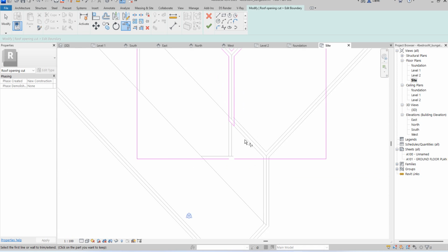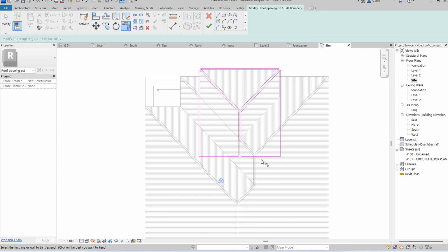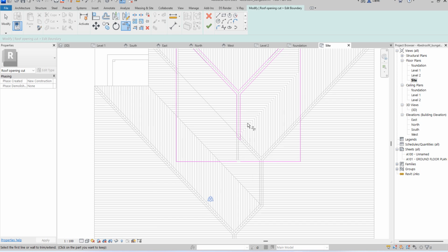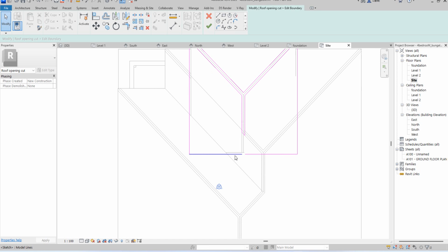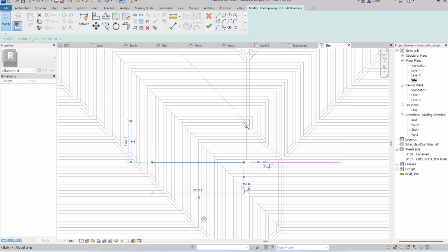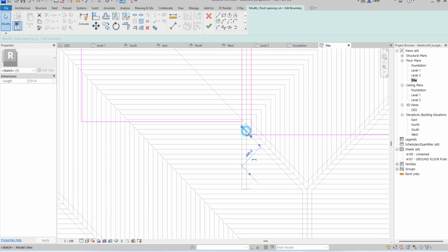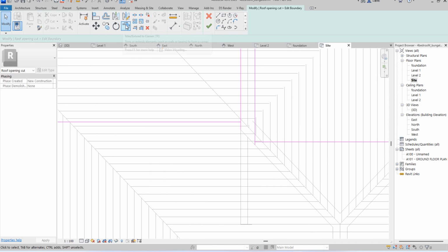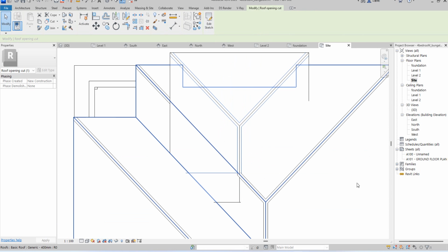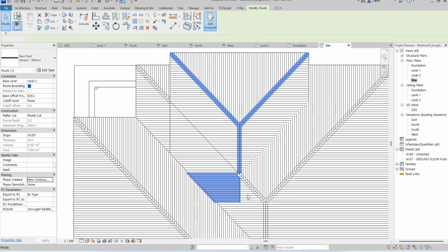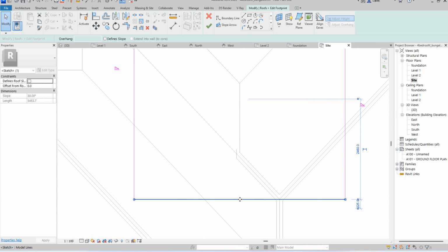So what we have done in that area, something is missing. Okay, so what we just need to do is that we should adjust this roof. Yes, we adjust that line. Just adjust. I think that's what we should do, not cut it off. So what we do here, just stick with that, then we adjust the roof entirely to suit that position. So what we do here is click and say edit. So in editing, we just need to stop our drawing here.